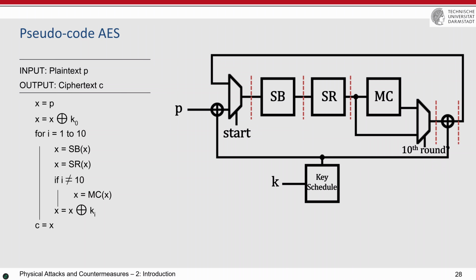One question that some of you may have forgotten: you need to put a register somewhere because it's a loop. You cannot build this with just a combinational loop. You learned this, as I explained, with Mealy or Moore machines, you need a register in this loop. Either you put one register here, or here, or here, inside the loop, or you put more registers. Because if you put just one register, for example here, the critical path delay will be something like this, large and long. Then it takes pretty long to perform one operation or one clock cycle. The critical path delay will be long. Then what you can do is put more registers inside.